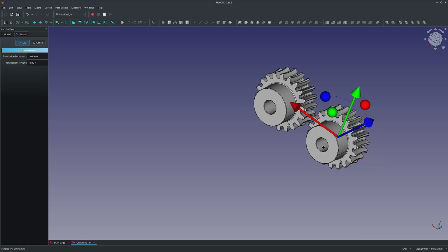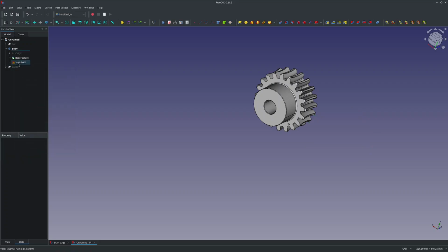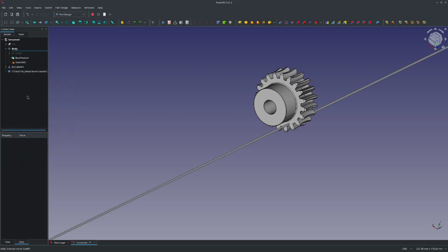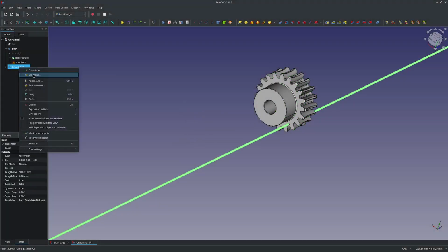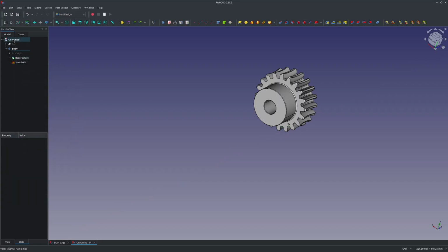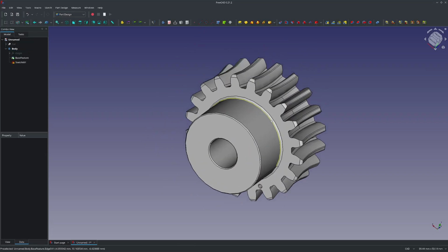So we can duplicate bodies and we can reposition bodies just like that. Now I am going to delete that body. And I can also delete this instance of cut. And the tree just keeps on coming, but we'll get there. And there we are. Right, so I'm back to my base feature where I'm at. So that should be everything you need to know.